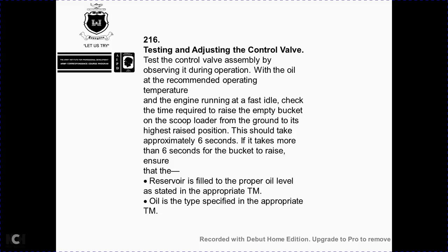Testing and adjusting the control valve. Test the control valve assembly during operation with the oil at the recommended operating temperature. With the engine running at fast idle, check the time required to raise the empty bucket. Raising the loader bucket to a high raised position should take approximately 6 seconds. If this takes more than 6 seconds,